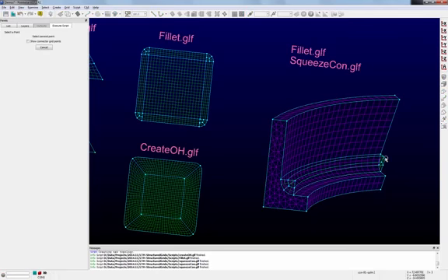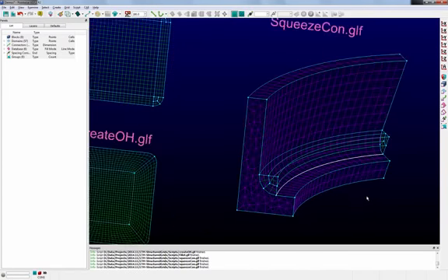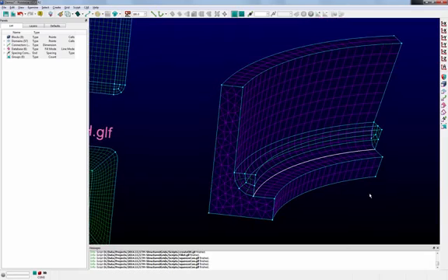Whenever you have connectors that closely resemble the final shape that you're after, this can be a very robust and quick way to generate this volume topology. However, if you have a lot of twist or a lot of 3-dimensional motion or 3-dimensionality to the connector that you're trying to scale, it's not going to behave very well. You kind of need to split that up into smaller chunks and handle each one individually. For instance, if you tried to take a line and scale it into an arc, there's really no way of doing that robustly.